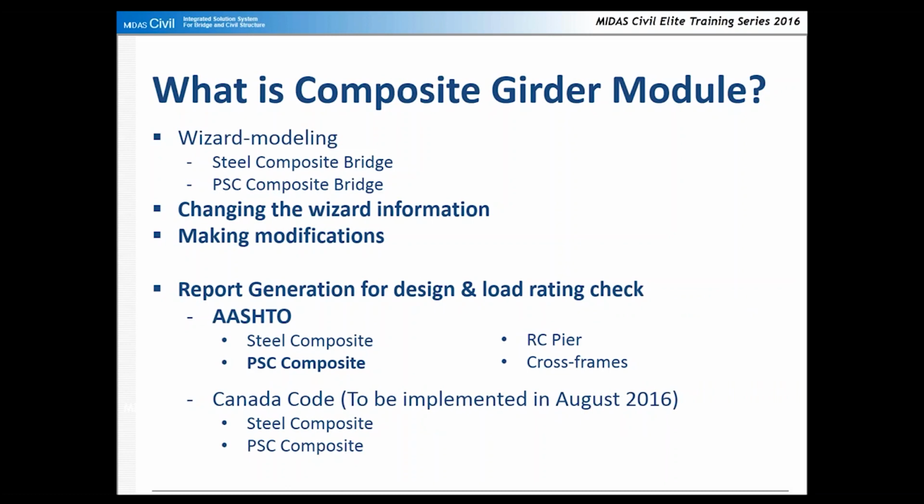Now getting into the training itself, what is the composite girder module and what am I going to focus on today among the features related to this module? For either a steel or pre-stressed concrete composite girder bridge, we have different modeling approaches. One of them is modeling using the wizard. Using the wizard, you can model steel plate girder or pre-stressed concrete composite girder bridges.